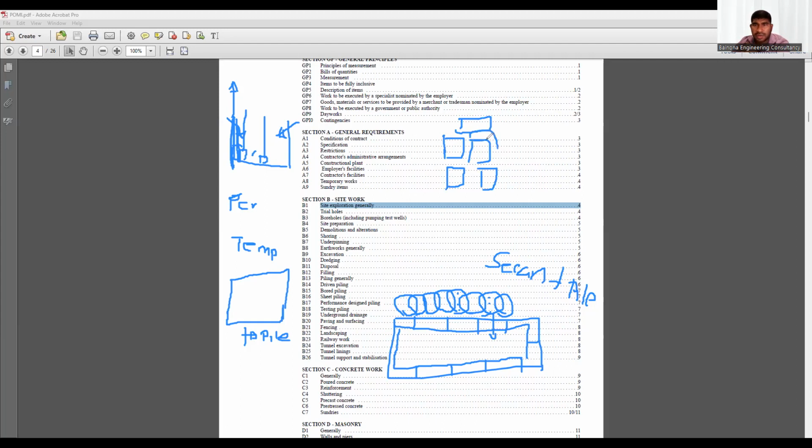For example, your width is 60 meter, and you get 65 meter, only 5 meter extra. So you don't have space. You cannot do open excavation, or you cannot do a temporary shoring and later remove it. For that purpose they use permanent shoring. Once they make a retaining wall inside, the shoring is of no use.